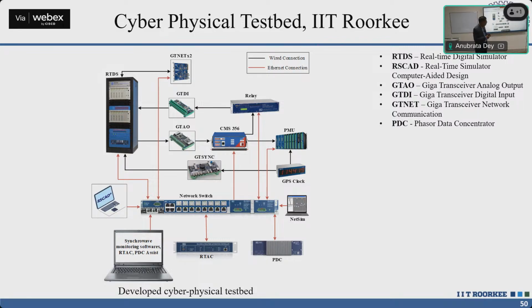Those PMUs which are available in RTDS itself are known as software PMUs. Those are not physical devices, just like when you place a load in any simulation, those are not physical loads, but you are using them in simulation. So here also you can use software type PMUs which can acquire the data.